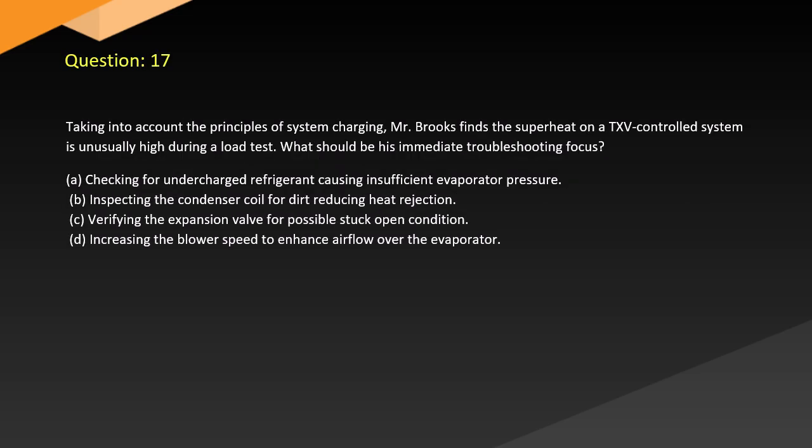Question 17. Taking into account the principles of system charging, Mr. Brooks finds the superheat on a controlled system is unusually high during a load test. What should be his immediate troubleshooting focus? A. Checking for undercharged refrigerant causing insufficient evaporator pressure. B. Inspecting the condenser coil for dirt reducing heat rejection. C. Verifying the expansion valve for possible stuck-open condition. D. Increasing the blower speed to enhance airflow over the evaporator.